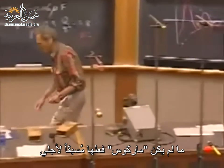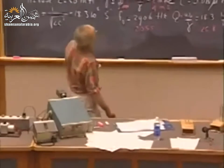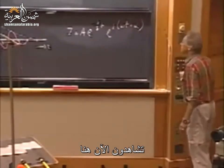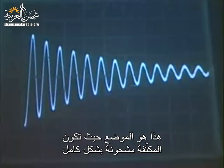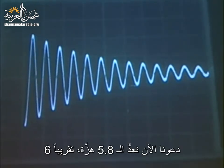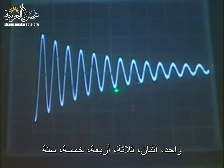I have to choose my channel, unless Marcos already did that for me. The surprise is already there. So you see now here the oscillations with about 2900 hertz. This is the location where the capacitor is fully charged, that is that Q max. And Q0 is right here at the left side at the bottom. That is where Q is 0. And let's now count the 5.8 oscillations, roughly 6. 1, 2, 3, 4, 5, 6.